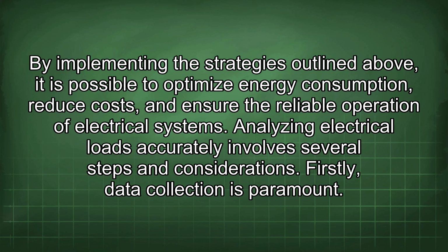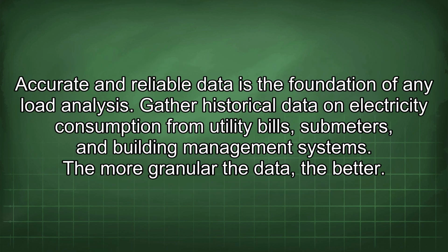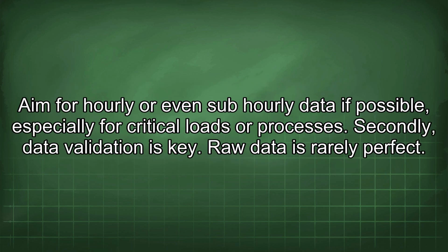Firstly, data collection is paramount. Accurate and reliable data is the foundation of any load analysis. Gather historical data on electricity consumption from utility bills, submeters, and building management systems. The more granular the data, the better. Aim for hourly or even sub-hourly data if possible, especially for critical loads or processes.